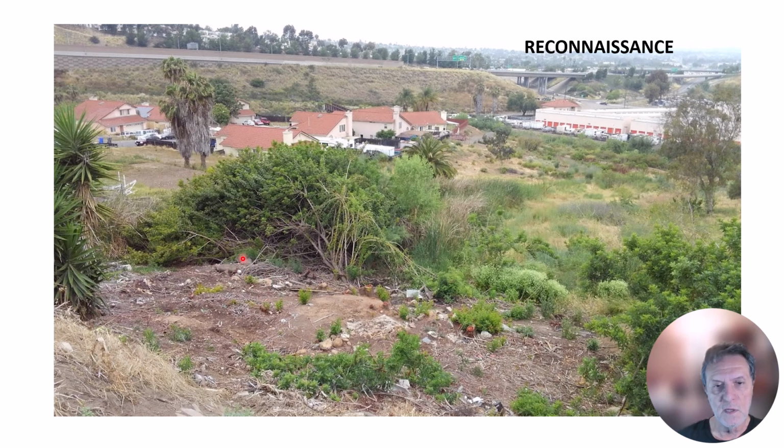This is all dumped fill. So you may not have seen that in aerial photos. It may not be on any maps, but it's important to note before you get started. You may want to tell the client that, look, we're going to have to handle this old fill, get rid of it, or reuse it, filter out the bricks and concrete blocks, etc. Okay.